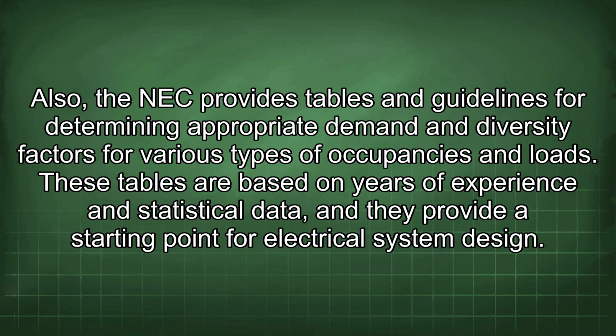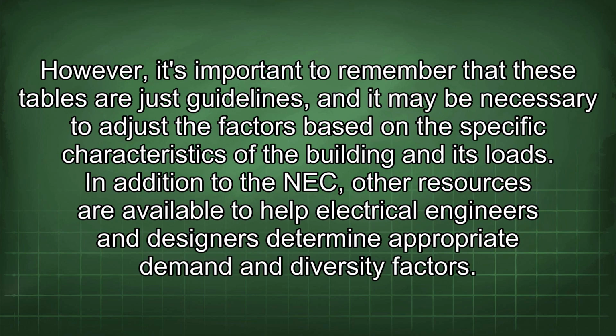Also, the NEC provides tables and guidelines for determining appropriate demand and diversity factors for various types of occupancies and loads. These tables are based on years of experience and statistical data, and they provide a starting point for electrical system design. However, it's important to remember that these tables are just guidelines, and it may be necessary to adjust the factors based on the specific characteristics of the building and its loads.